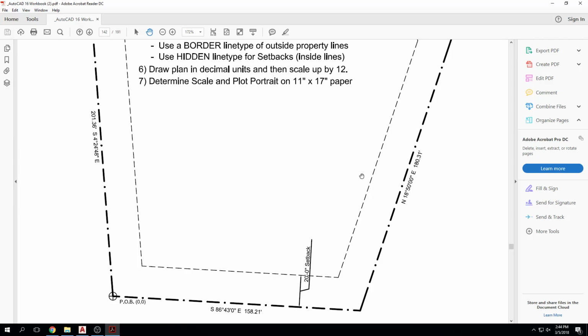So we're creating a dimension style just like we would any normal architectural dimension, but we're changing some of the settings so that it is specific to a site plan, okay? As a civil engineer, something you will use constantly, right? As an architect, you'll use it several times throughout a project, right? Probably the first time you'll use it is likely going to be when you draw the site plan for whatever project you're working on, right?